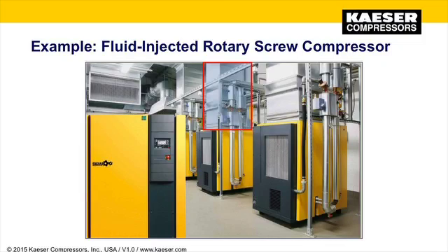The hot air is used in cold weather periods to heat up the compressor room and the adjacent areas. The hot water lines, which are shown on the bottom right-hand side in the blue frame, along with the pumps, valves, and controls, are being used to heat up dipping baths for cleaning sheet metal prior to powder coating.